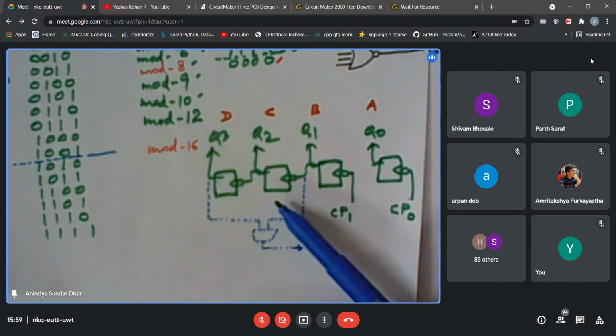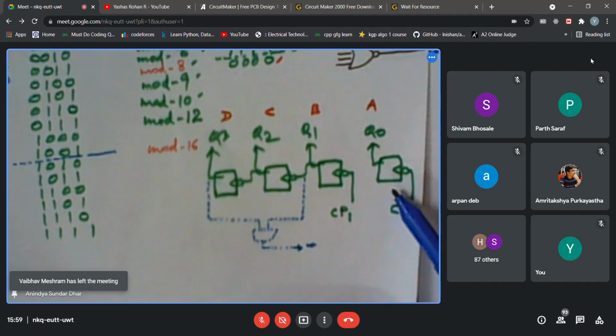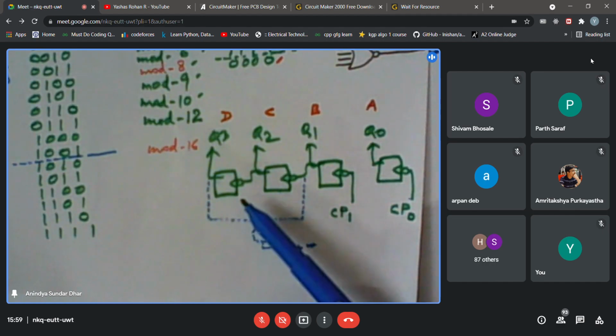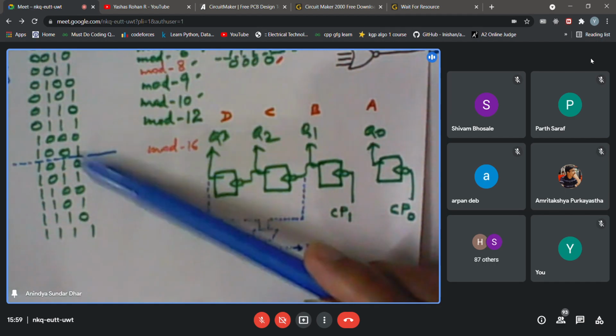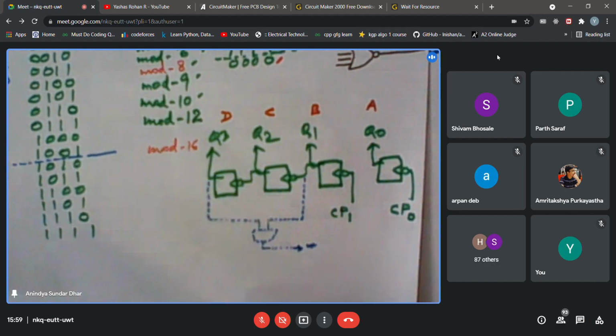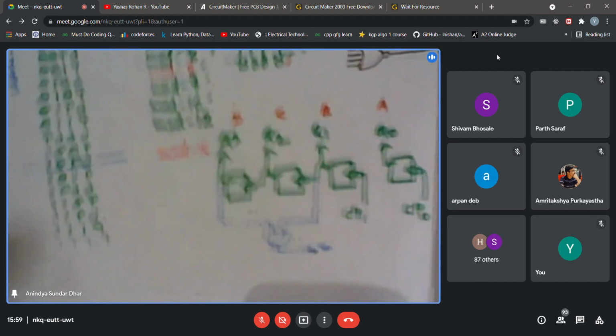But still this flip-flop you can reset from the external pin 2 and pin 3 always. It need not happen just because of that internal reset, because as you can see, from 9 when it is going to 10 or 0, in either case it is automatically going to 0. So I may not have to have an explicit reset in that case. So please check the manual or the data sheet.